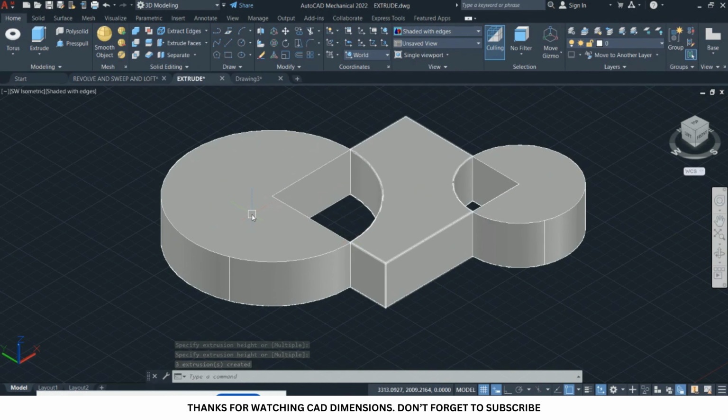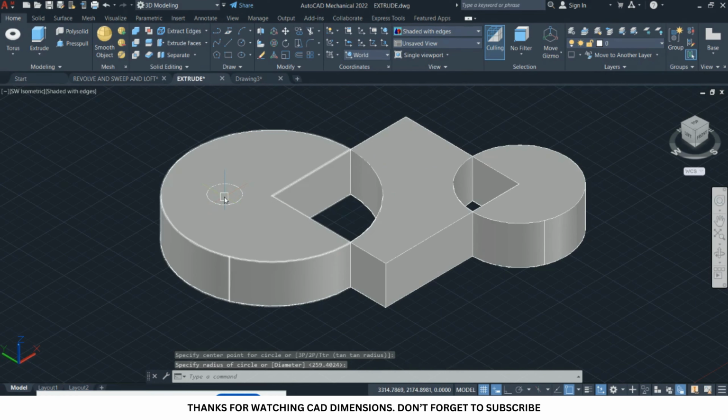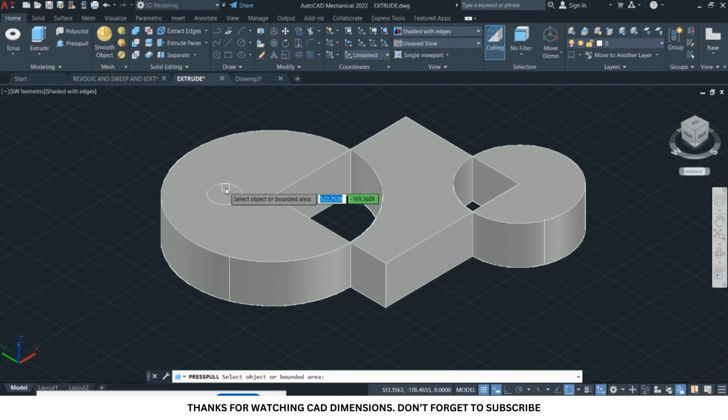Okay. Another thing with the press pull is that you can also use it to separate or create a subtraction within a particular model. So for example, let's say I have a circle I want to introduce here, and this time around I want to create a hole. I can use the press pull to do that.